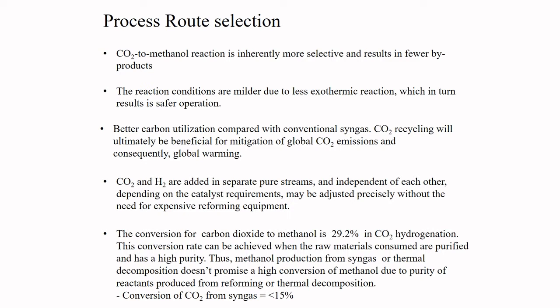For process route selection, CO2 to methanol reaction is inherently more selective and results in fewer byproducts. The reaction conditions are milder due to less exothermic reaction, which in turn results in safer operation and better carbon utilization compared with conventional syngas. CO2 recycling will ultimately be beneficial for the global CO2 emission.